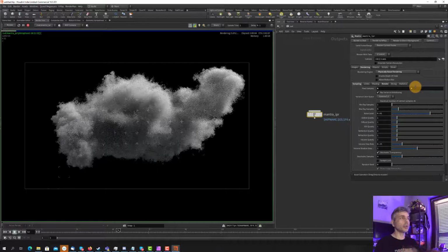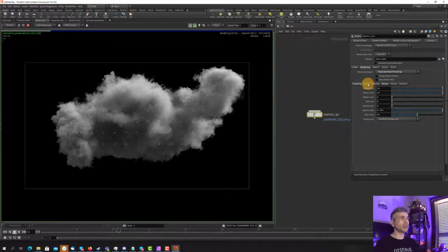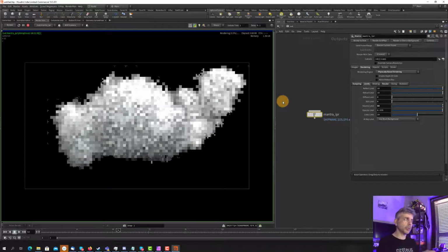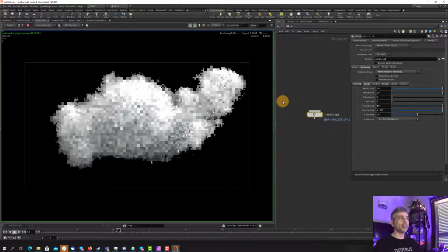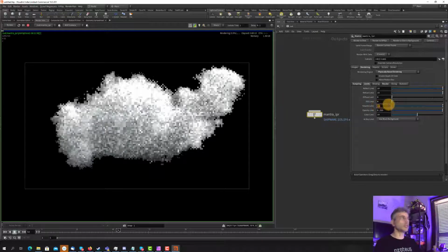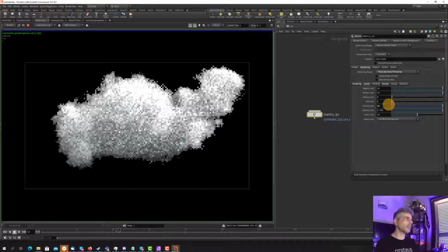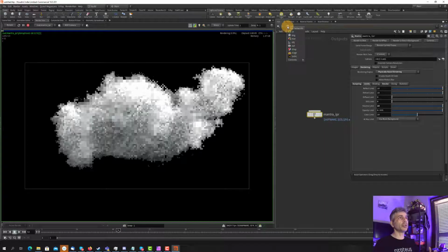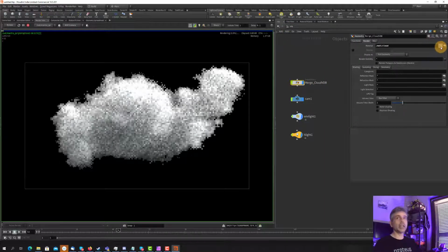Now something related to the rendering. We move to the physically based rendering, just because it's the best one. It is a PBR render. About the quality, pixel sample can control globally the quality, and 6.6 can be enough. We should work more on the anti-alias and sampling setup, but you know, we are not taking time to talk about Mantra, so it is better to play more just with the global parameters.